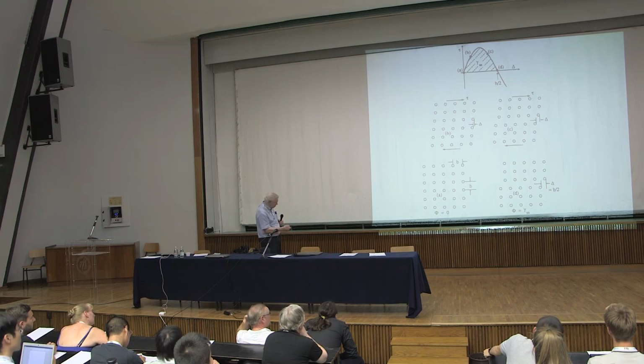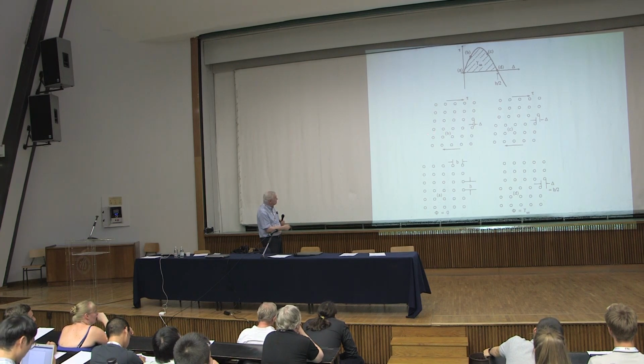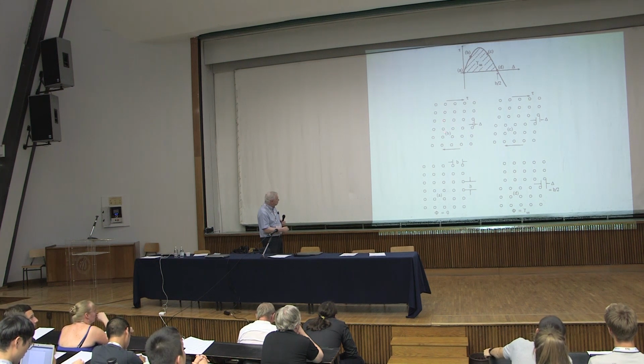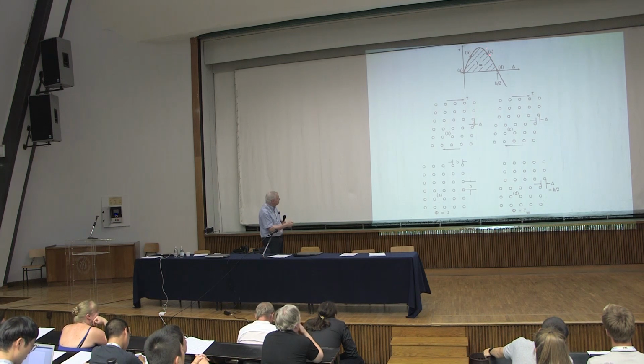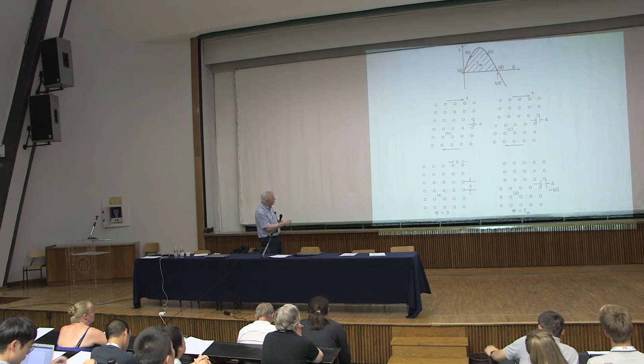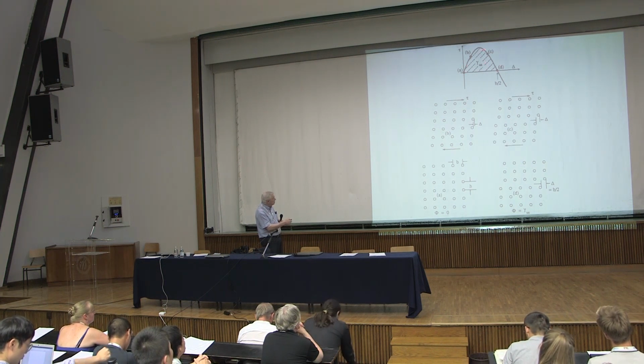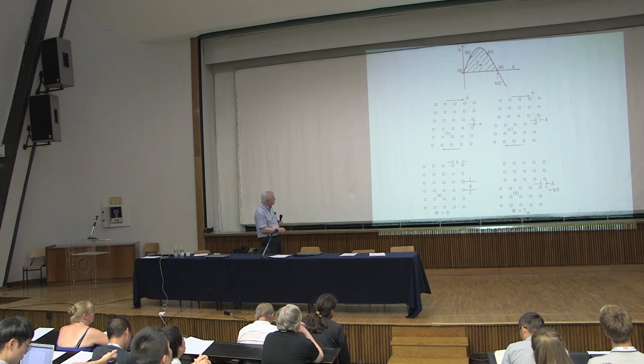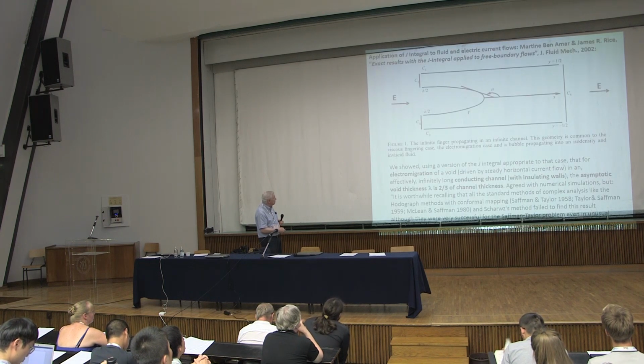Oh, here's a picture of that schematically of what's involved in that unstable stacking energy. You imagine you're shearing these blocks of atoms, and as you shear, ultimately you're going to come to a peak load, and then it's going to be unstably downhill from there. But this area under the stress versus amount of slip curve defines that so-called unstable stacking energy. So that was, again, another application of J.